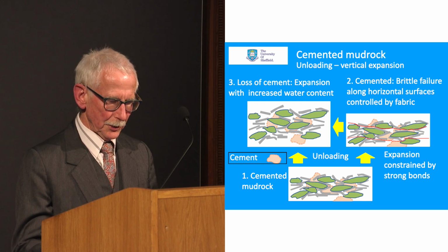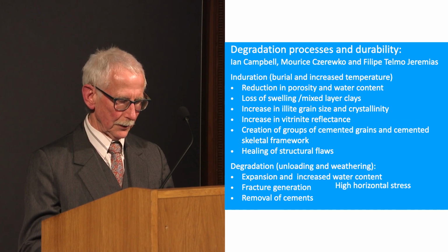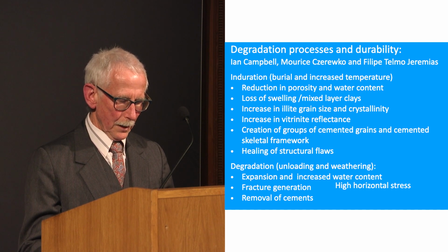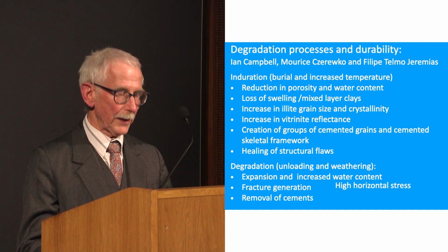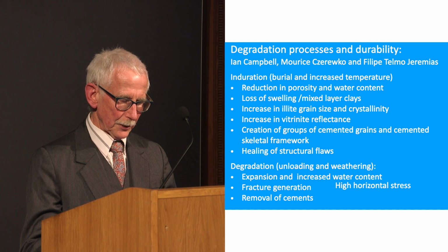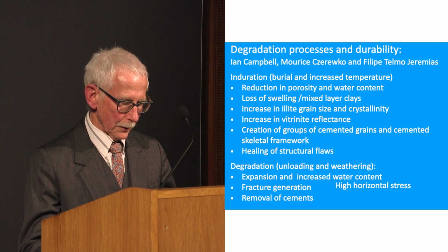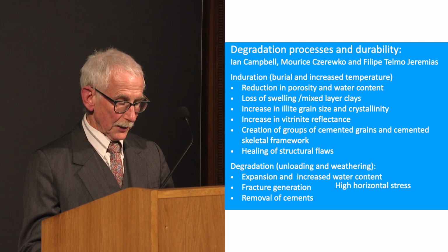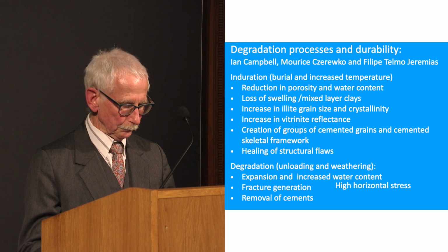This summarizes the changes during burial and exhumation. The main points are the reduction in porosity and moisture content, loss of swelling clays and cementation during burial, and exhumation, which results in expansion, removal of cements, increased water content, and fracture generation. So although mud is formed eventually, the assemblage of minerals will be different from the original material. It will be dictated by the current weathering environment and not the original mud before it was buried.